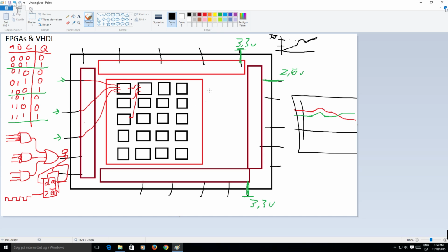The last thing I want to mention is that we can have one or more phase lock loops inside an FPGA. You could of course always divide the clock down using the flip-flops, and then maybe you could divide the clock signal by 16, and you could use that for some other part of the FPGA's logic. If you need to send data over UART, or you need to send it to a character LCD display, you might not want 100 or 50 megahertz of data going to that. You could use the flip-flops to divide down the clock, but that would take hardware, and you can really only get the division in powers of 2 of the main clock, unless you don't care about the propagation delay.